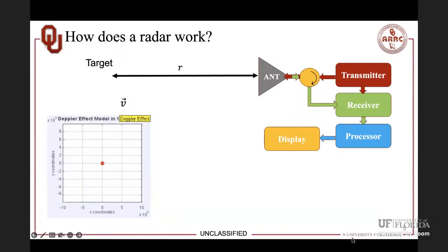For example, radar is just like that bat. If you think of that, you send out the sounding things, right? You don't hear it, it's actually sending out a pulse. Inside a pulse there is actually a frequency modulation, or chirping. Radar does that too. Instead of sending out sonic energy, radar sends out electromagnetic energy, which turns out to be waves. The transmitter basically does that. It generates a particular waveform, or you can think about it as the chirping of the bat.